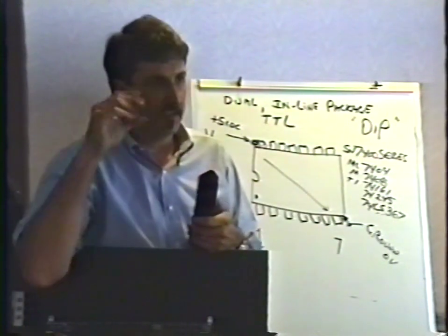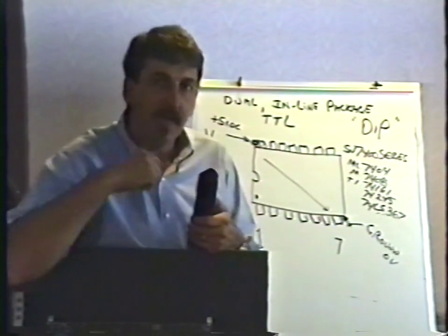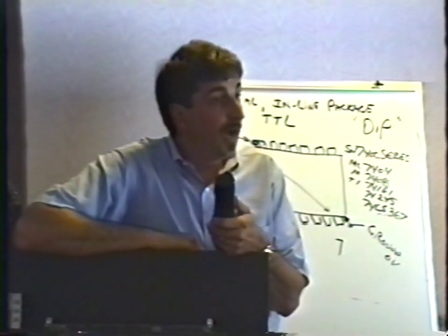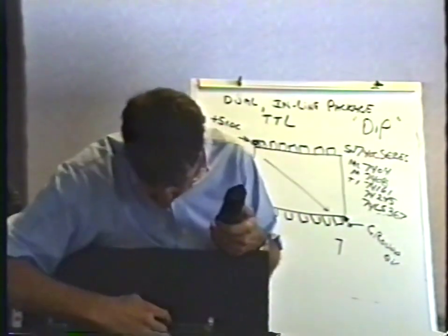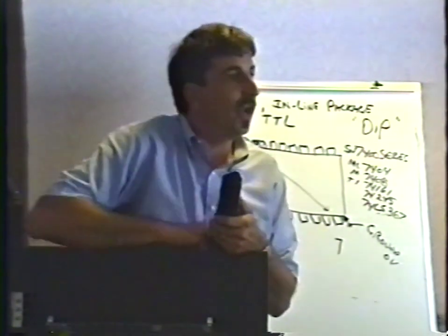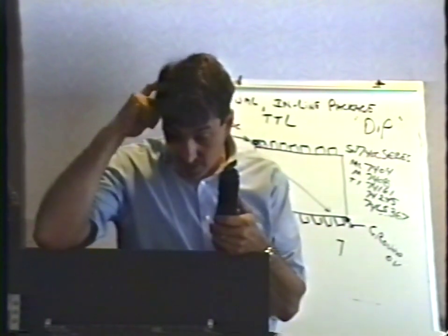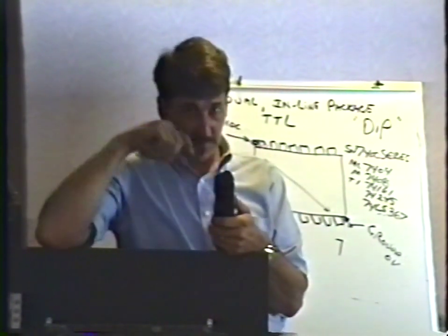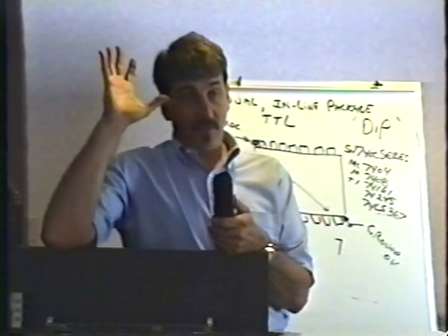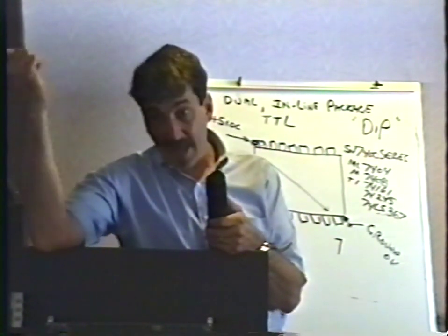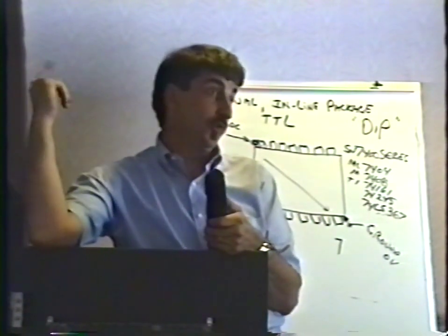The test does a little self-test dance that it does, checking its internal stuff. Just to verify, Claude checked it across this chip right here, 5.09 at this point. Fine. Works great. This monitor does have a problem, and we'll talk about it Thursday. It's real bright on one side and real dark on the other. It has a typical capacitor failure. It happens to be capacitor C702.